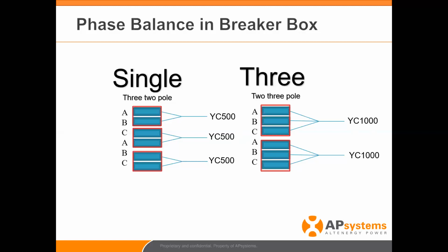If you looked at the PTC, what they say is what you're practically going to get based on conditions, weather conditions, soiling, angle, everything, you're looking at a 302 watt PTC. And I said, you can use it all day long. You might clip 2 watts, but I don't think you'll ever see it. And they've installed it and are quite happy with the performance.